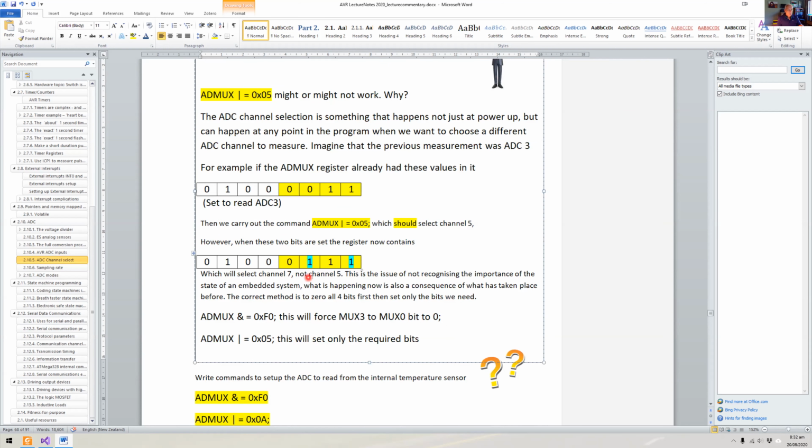So you must think, what I've got to do is zero all these bits here. A couple of ways you could do that. You could, of course, zero each one individually, but you could just write a line like this, which will allow you to zero those bits there. You need to make sure that you understand what's happening in a line of code like this. It's really important that you are ANDing some bits with 1 and some bits with 0, and the bits that are ANDed with 0 will be forced to clear to 0, and the bits that are ANDed with 1 will stay as they are.